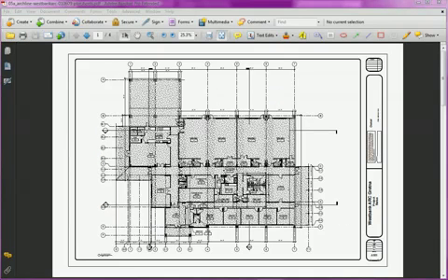This is the first progress upload to the architect in the first week of production. These progress uploads should occur on a weekly basis. Typically, an upload includes exported files into AutoCAD format for the architect to send to his engineering consultants to use as backgrounds for their drawings. The poche here is part of the concrete slab in the model, which gets turned off later.